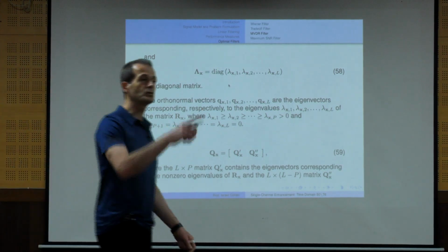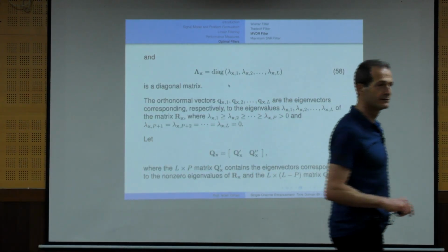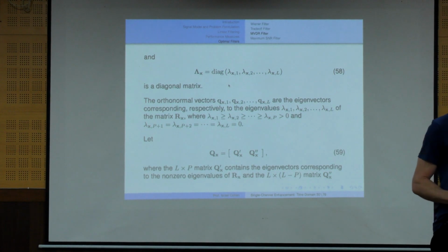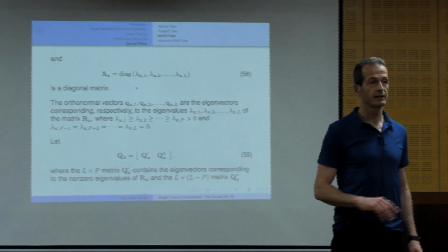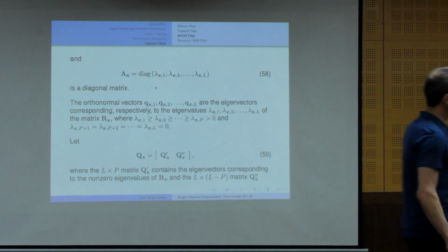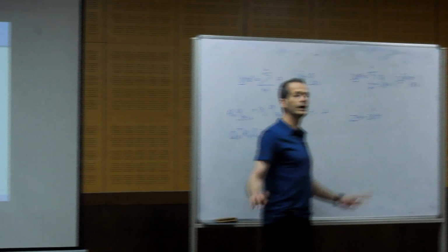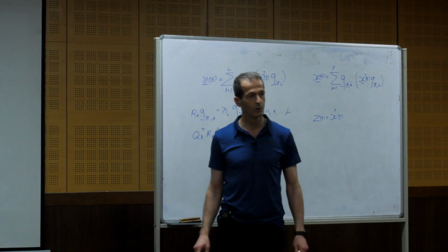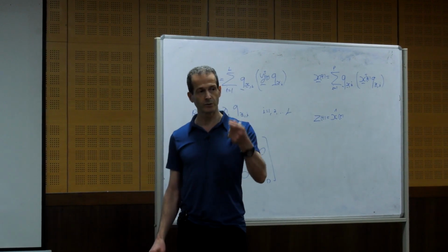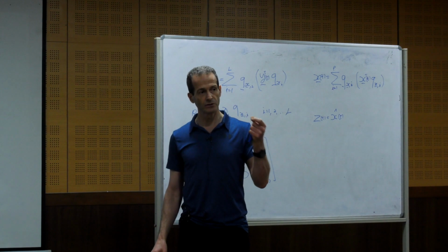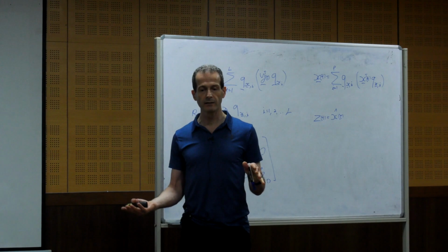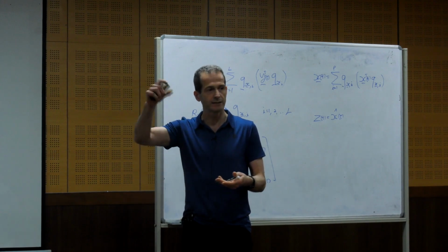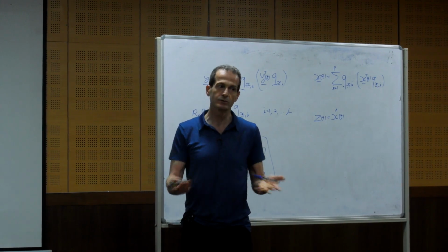If P is L. Good question. If P is L, what does it mean? What will happen with the MVDR? No noise reduction. It doesn't do anything. Actually, Z will be equal to Y. No noise reduction. Why? Because the constraint is no distortion of the signal. And if P equals L, we don't have any noise to reduce without distorting the signal.